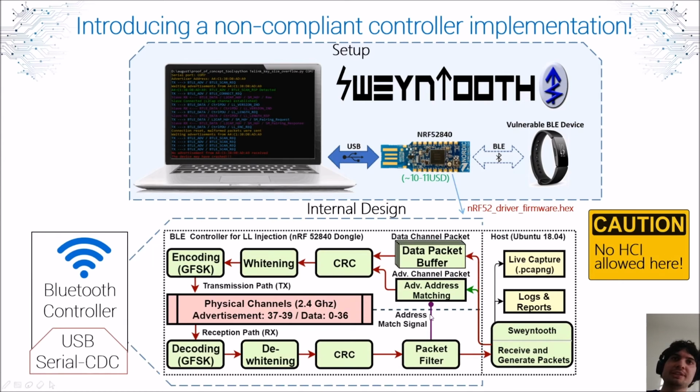In elaborating the design itself, we created this firmware and called it a non-compliant firmware, because the whole goal of this design is to forward link layer packets to and from the central and the peripheral. And because HCI is not sent over the air, it is possible to move the link layer from the controller to the host. So we are eliminating the need for HCI by creating the link layer procedures totally on the host, more precisely on the model of the Low Energy protocol, and only handling on the firmware the essential time-sensitive tasks such as channel hopping, and also detecting the correct channel to switch to and from, while they communicate with the peripheral.